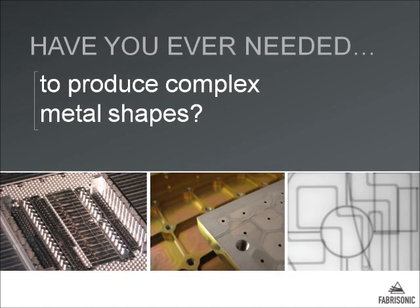As with every other additive manufacturing process, UAM allows us to produce complex metal shapes that you wouldn't be able to make any other way with any other process. Because we're building one layer at a time, we can create very complicated shapes. We can lay one layer of material, which is typically on the order of 5 to 10 thousandths of an inch, and then come immediately after welding it and machine very fine features.